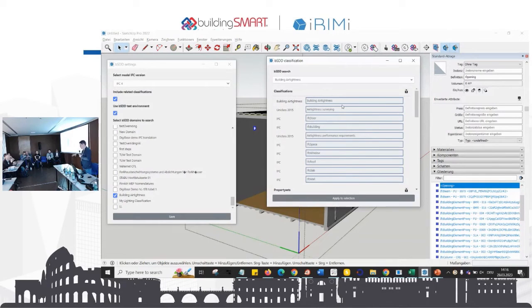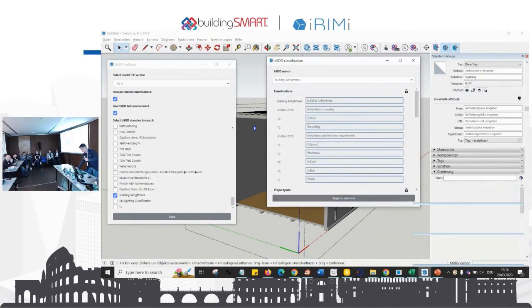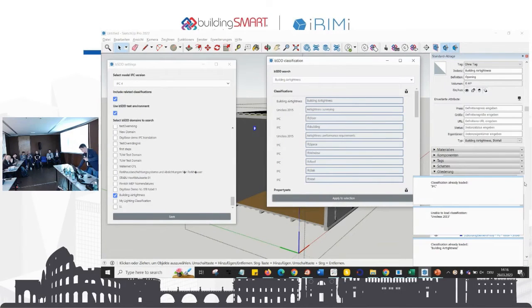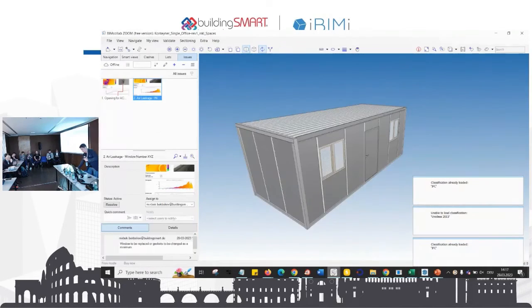You can directly use the existing IFC schema if you're not sure which entity or which property set to use. So you can simply map, apply the selection, and it will be mapped directly, as you can see. Now I will go through these mappings, and we have a bSDD, right? I mentioned, you remember, I did some work, like, let's say, homework.